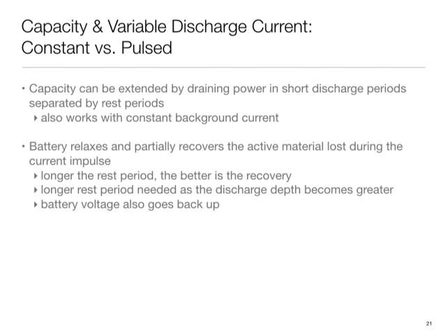The other one, which he asked questions about earlier on, is constant versus pulse. Capacity can be extended by pulsing the system, by stopping using it and restarting. So I'm increasing the time to finish, but I'm extending the battery life. Now again, the story is not that easy, because unless I truly shut the system down, I will also have some impact because of leakage. But what's happening from a battery perspective is that by letting it relax, it rejuvenates, and therefore the material inside the battery evens out and recovers. It's ready to supply more charge.